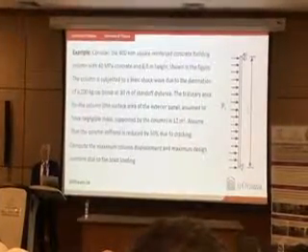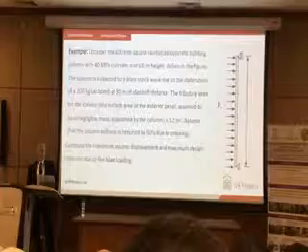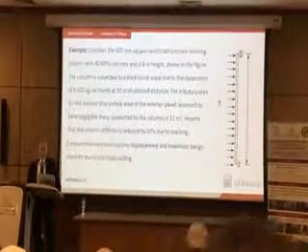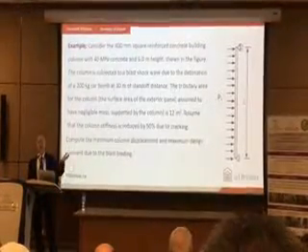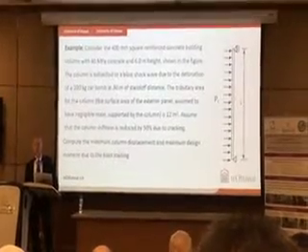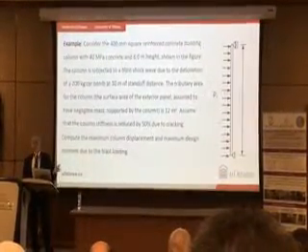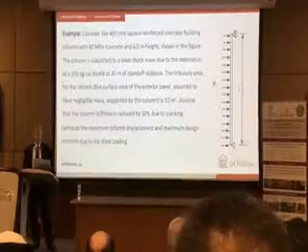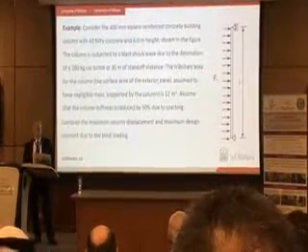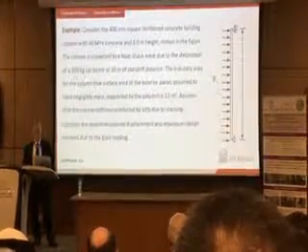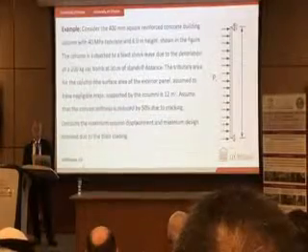This is a column, a 400 millimeter square reinforced concrete column of 6 meter height. It's an industrial building made out of 40 MPa concrete. I need to know rigidity, so strength has to be specified. And it's subjected to a 200 kilogram car bomb placed at 30 meters.